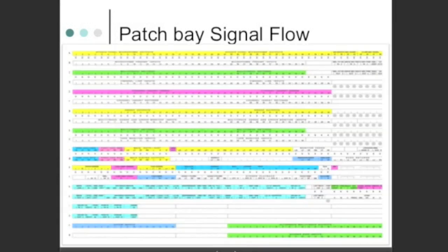This here is a very simple diagram of what a recording studio patch bay would look like. You've got this top strip of patch points being the cable that comes from the panel from the recording area with the cables with the microphone feed on it, and there's a patch point there, and then it feeds down. The second row is the input to the console at the microphone preamp inputs. Then you've got some sort of an insert.